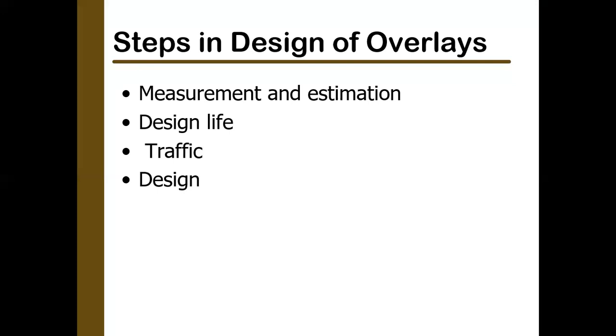The design life can be estimated in terms of what we call the remaining service life of the pavement. For instance, if the pavement was constructed 20 years ago, and from the estimation of our tests we find that the remaining service life is 4 years, then we can design the overlay for 4 years.